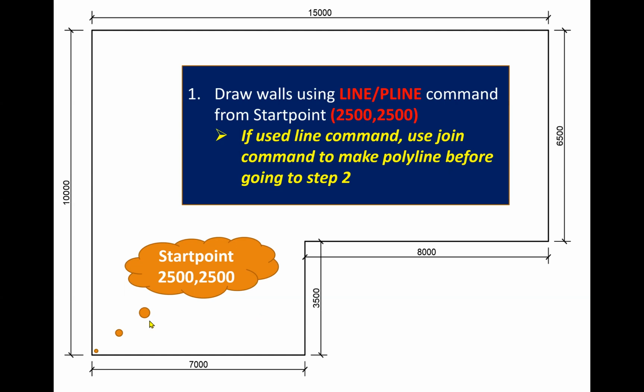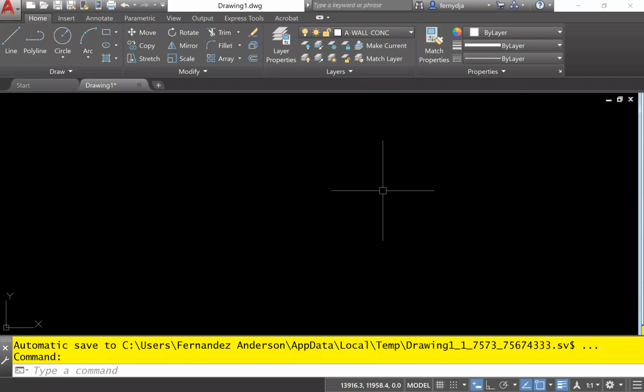All right, so we will start at the lower left-hand corner, and using these external dimensions, we're going to go east, then north, east, then north, then west, then south to close the shape. All right, so let me get back to the AutoCAD screen where we can demonstrate that. So we're in the wall layer, and our drawing limit is already set, as well as our precision.